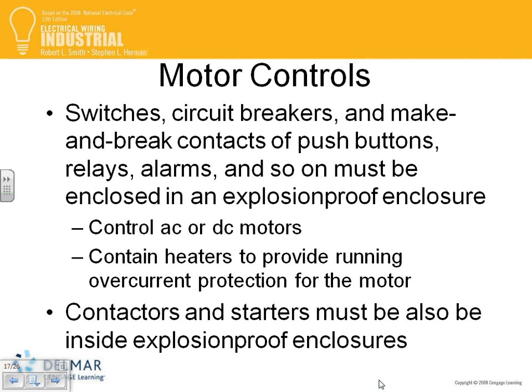Motor control, guys, if you use any of these, and I summarize this as any device that you use, Jim, to interrupt the power or consume power, this has to be an explosion-proof device in a Class 1 Div 1. And you have to seal around it. That's really summarizing the whole deal.